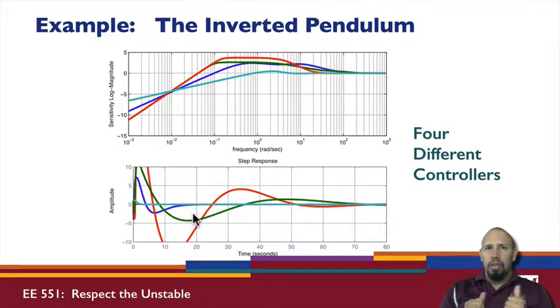Having those two things are in conflict with one another, whereas the control strategy for this one uses two controllers, one to help with the tracking, the other to help with stability. As a result, it's able to give you a much better response, and the sensitivity function looks better. So I thought this was a good example to look at.